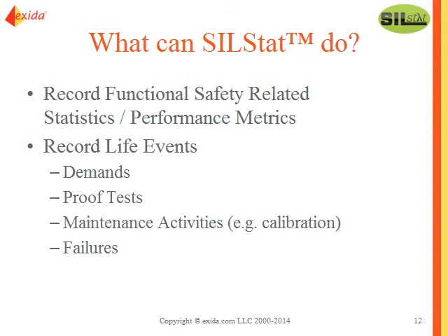But at the same time, SILStat can be used to document that you have performed your proof test, and you can use it to show compliance to the requirements of IEC 61511. Show that you're compliant to, I've done my proof test per the proof test schedule. You can use it as a scheduler tool. Maintenance activities. Some products require specific maintenance. Well, we could talk about